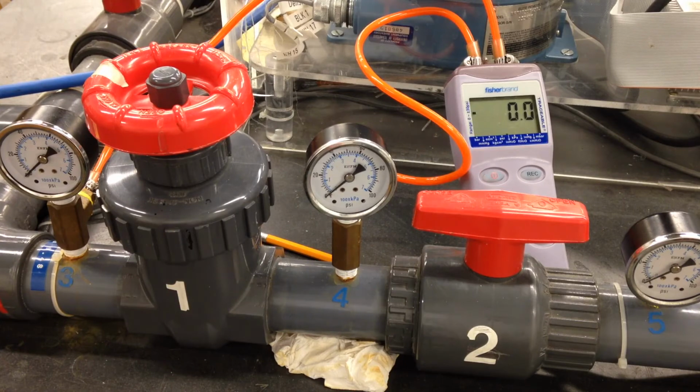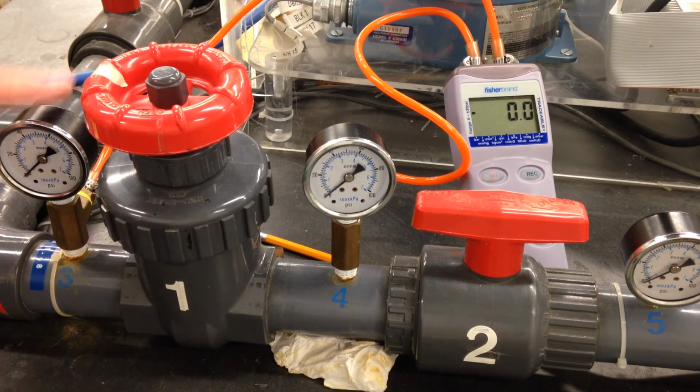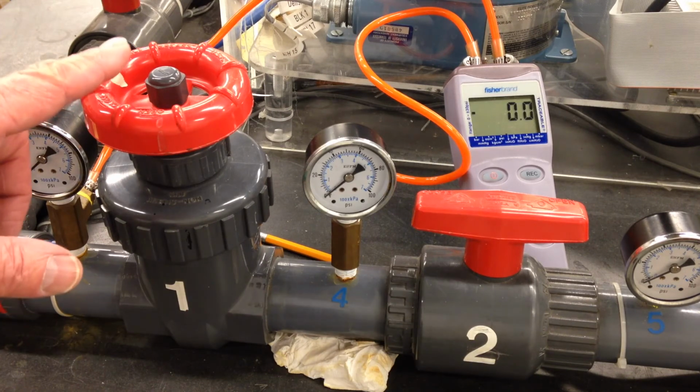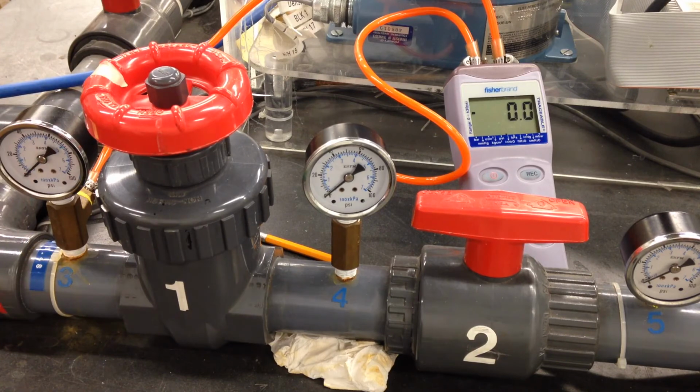Now we're going to do the gate valve experiment. In the gate valve experiment, as you can see, we have a digital manometer, and it's ported on both this side and this side, right behind these two pressure gauges. And we're going to measure at different openings of this the head loss across it. And we're going to compare that to the flow as I showed in the theory, and we're going to compute the K value.